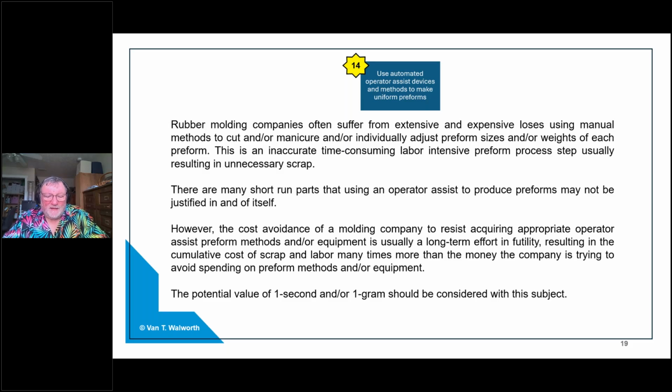It can't happen. And something like that, to its own scale, is what happens when I put preforms in one at a time manually and go back and get some more and place them on the mold in some order. The preforms that went against the mold first see the most heat the soonest and are sitting there until the last part goes in. Whether I dump them in as a pile and then start spreading them out, the point is all of the preforms did not go into the cavity and touch the hot surfaces of the mold at the same time.